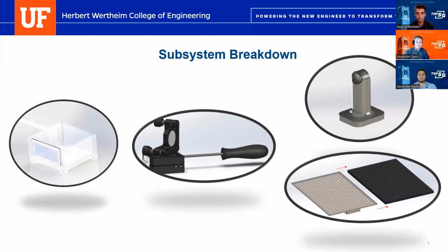The path switching subsystem redirects the 438 nanometer laser in between the light sheet and optogenetic stimulation paths while causing no crosstalk between lasers. The path switching subsystem comes equipped with a 3D printed hinge adhered to the side of the customer specified magnetic mirror mount. The magnetic mirror mount is able to be pried off of its bottom plate using a ball end screwdriver to change the desired path.